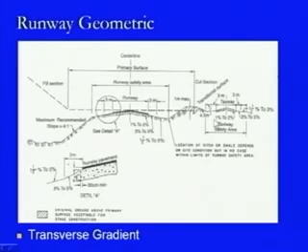That is the approach area which we generally consider, and this is a normal terrain condition which is shown here. With respect to this normal terrain condition, after this point of the approach condition, the transition surface will start, as we have seen in the case of obstructions on any airport, and this transition surface will then transform into a horizontal surface after this.